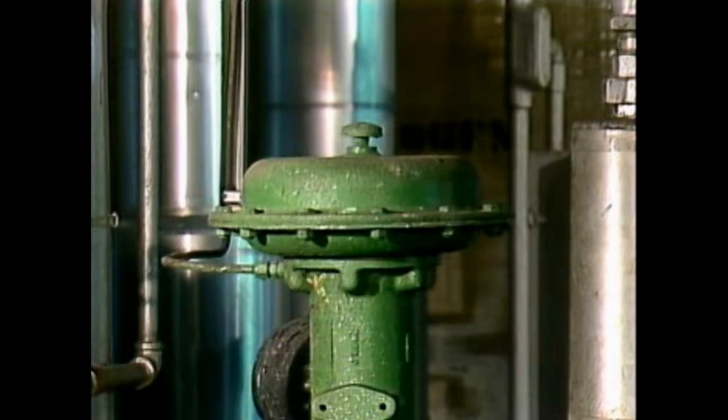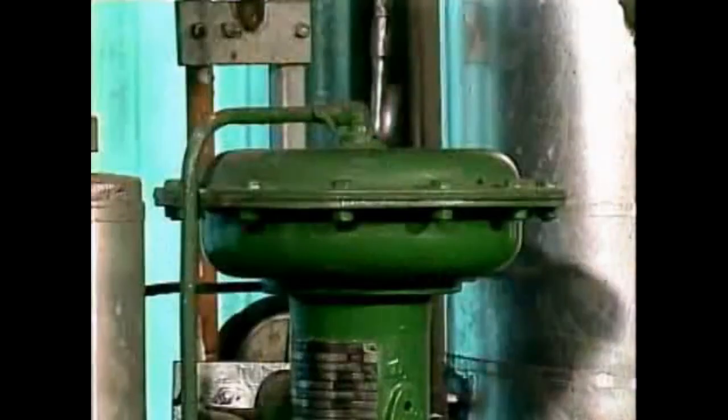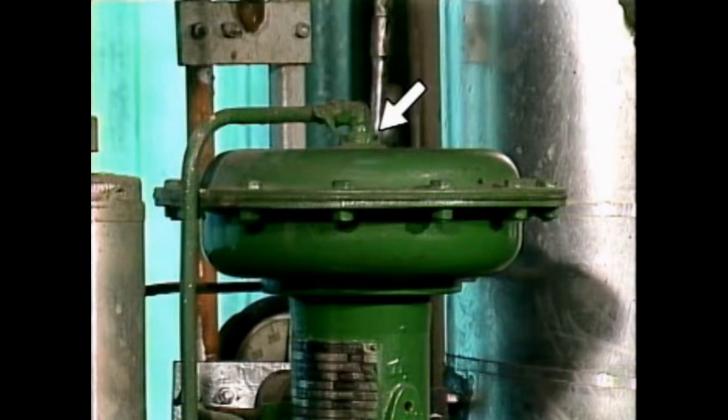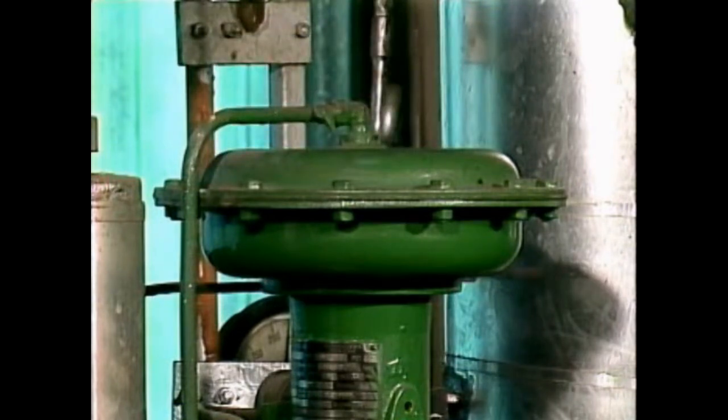A diaphragm actuator with an air line to only the lower chamber is typically an air-to-open, spring-to-close type, which causes a control valve to fail closed. An actuator with an air line to only the upper chamber is typically an air-to-close, spring-to-open type, which causes a control valve to fail open.